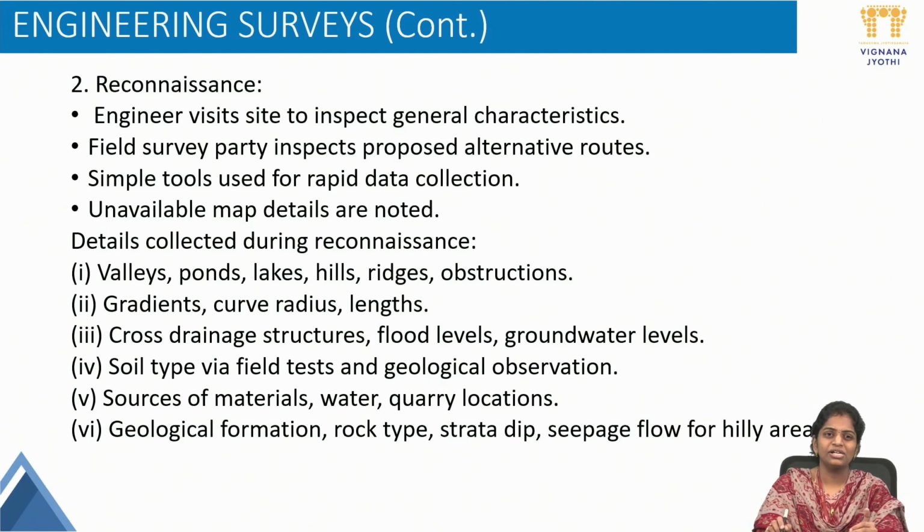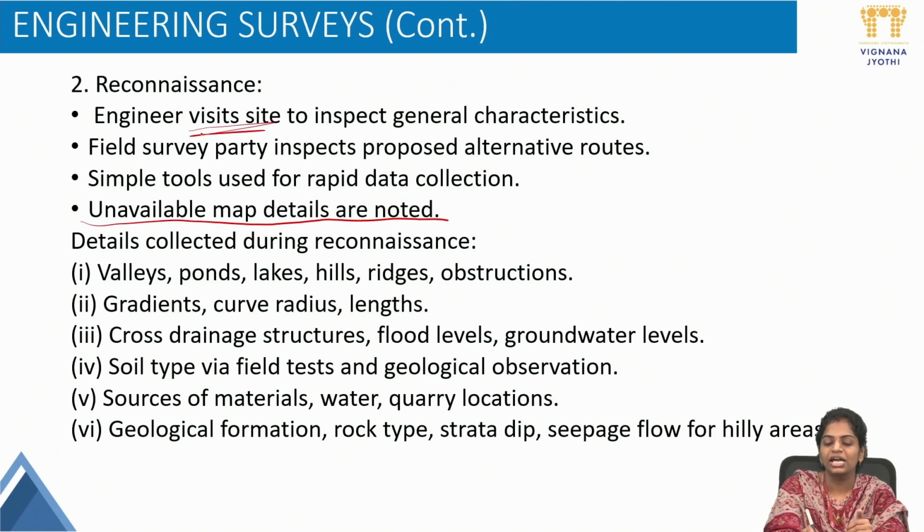Next, after the map study, we have to go for reconnaissance survey. Reconnaissance survey is nothing but the engineers visit the site to inspect general characteristics. In the second stage, the engineer will visit the site and will get the details which are not available in the map. That is important. Already in the first stage we have noted map details. In reconnaissance survey, after going to the field, unavailable map details are noted.